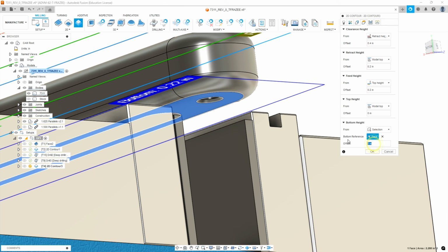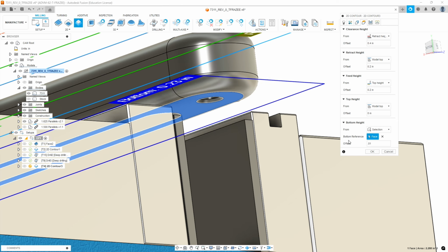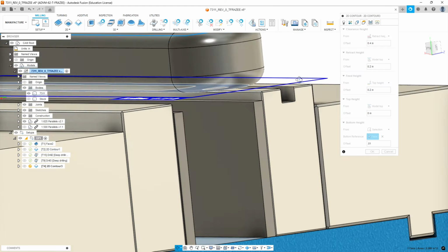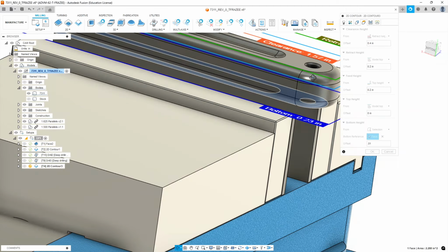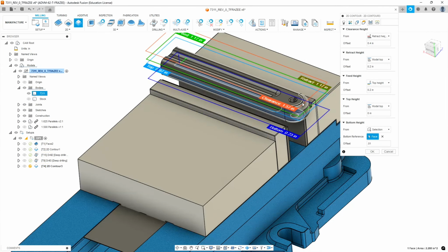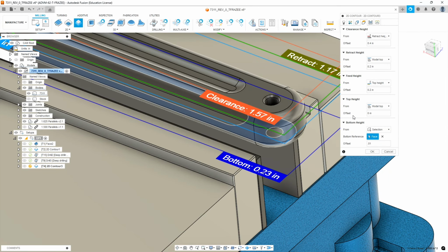And we want to go slightly deeper, so we're going to go 10 thousandths. Now our drill bit went 100 thousandths deeper, but that's with a drill point. We just want to go enough that we're sure to have a fully established hole when we flip the part over, and avoid significant flash of material if we have a variance in the thickness of our part.